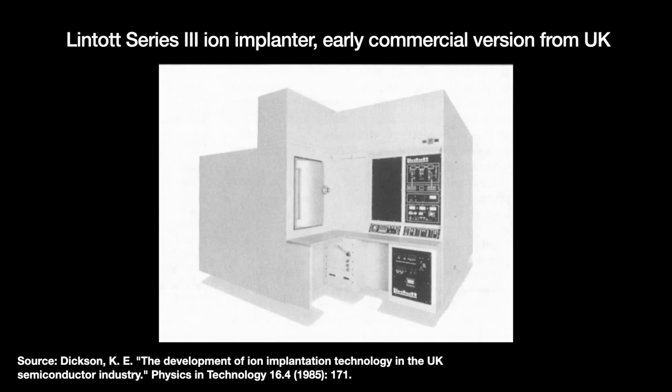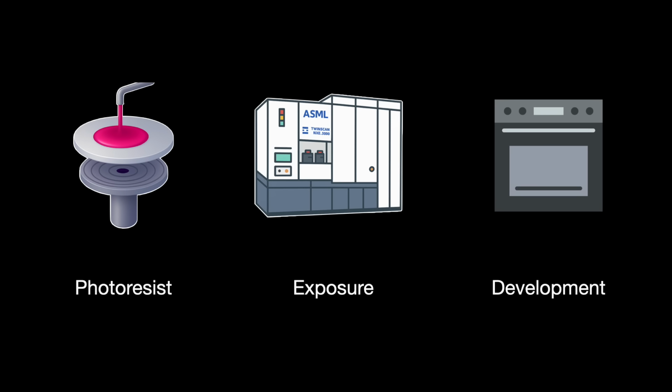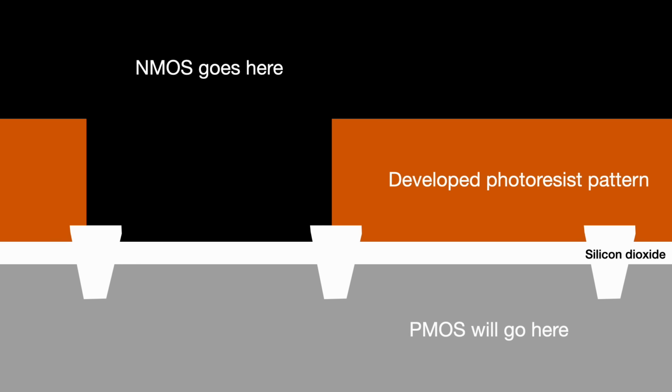Patterning means lithography, and you know what that means. We again slather the wafer with photoresist, expose it in the exposure tool with the photomask, and then develop the exposed image. The mask's image contains holes where the wells will be. During image development, the 300 to 800 nanometer thick photoresist layer is hardened to quote-unquote resist the forthcoming ion implantation, which can be damaging.